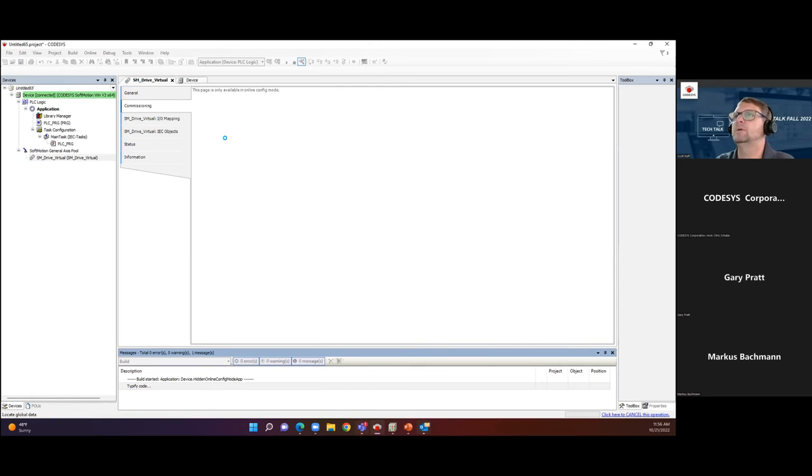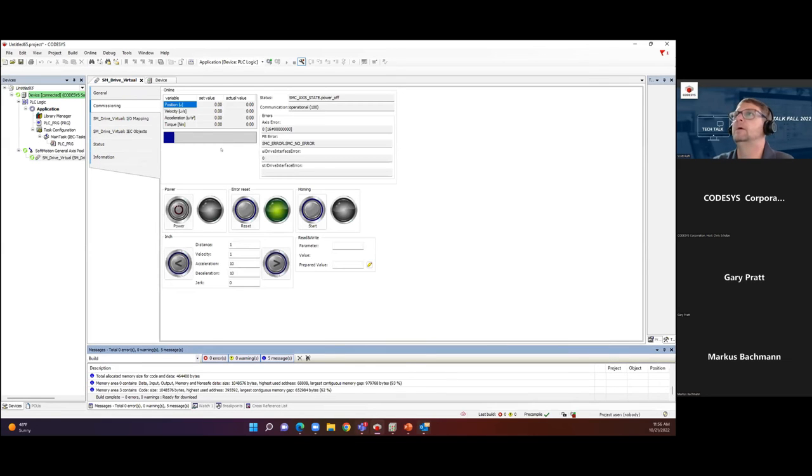Okay, so while it's building, it's getting ready. It's pushing me into the commission mode and building the interface. There's the interface. Here I am. Right now you can see that I have 0 position, it tells me the axes, and it says right here, power off. So I'm going to do a reset and power the system on. Now it's at a standstill state. I can now give it a distance. I'm going to say 100. And I'm going to give it a velocity of 100, acceleration of 100. I'm just punching in numbers so I can show you it moving. Oops, I'm going to give jerk 1,000.